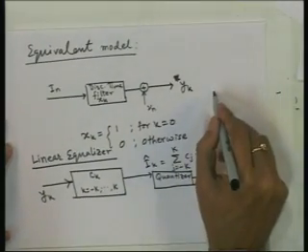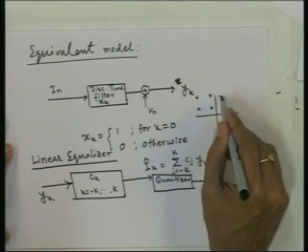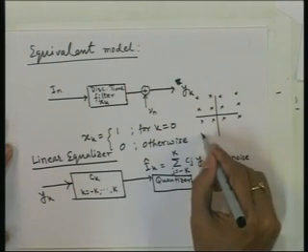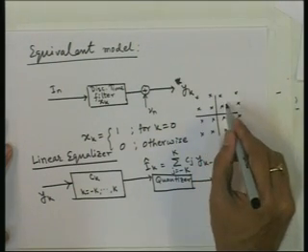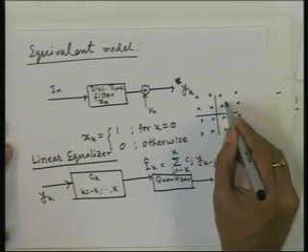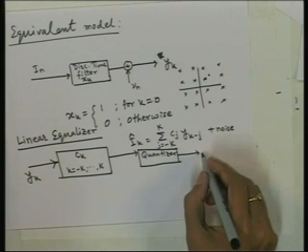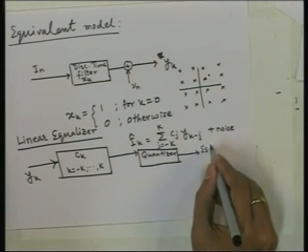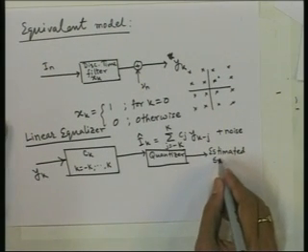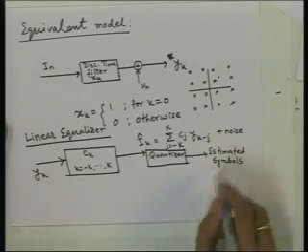So, if you had a 16 QAM constellation, if it was a complex constellation, this I k hat may be a point somewhere here, and this quantizer will choose the nearest point. It will quantize to the nearest constellation point. That is what the quantizer does. And these are the estimated symbols. These are the estimated information symbols.